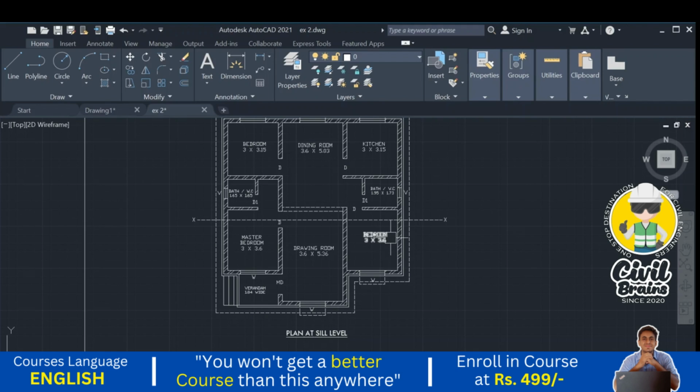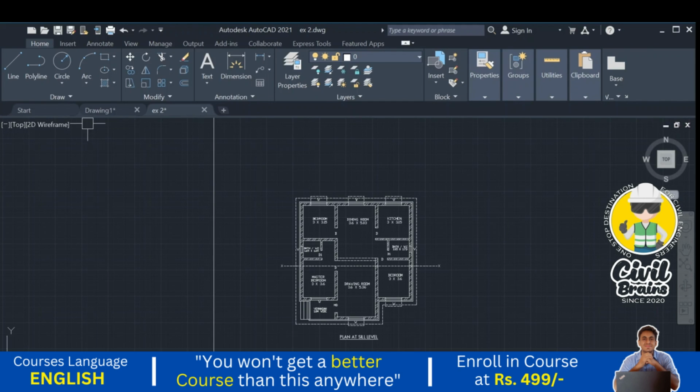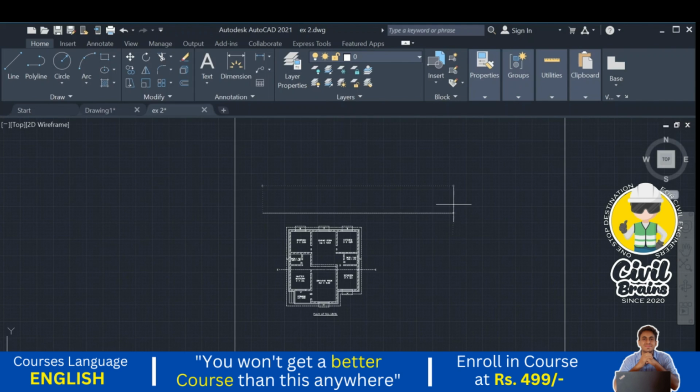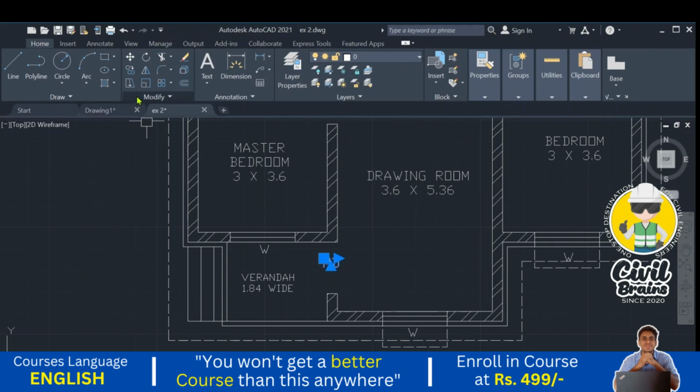While doing the elevation, first we need to understand the level of the ground and the type of the ground: whether it is a sloping ground, whether it is a straight ground, whether there are any objects over there, or any undulations. We need to identify that. In this example we are considering a straight, plain ground, which has very minimal undulations. So the first step, I am going to draw a ground line here. This is our ground line, and I just write here ground line.